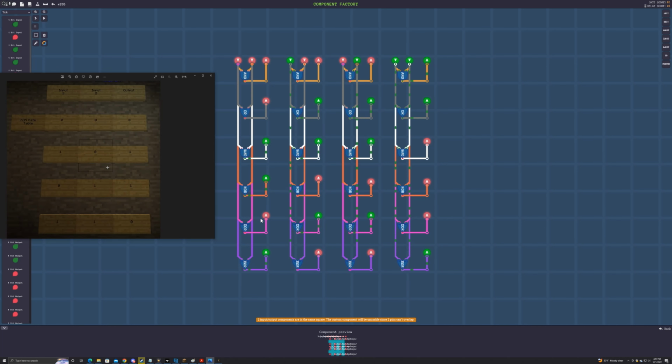For the XOR gate, when there's no signals coming in, 0, 0, there's no output. It is still 0. For the XOR gate, again, when there is an input in 1, there is an output. When there's an input in 2 but not 1, there is an output there again. But when there's an input in both 1 and 2, there is no output.